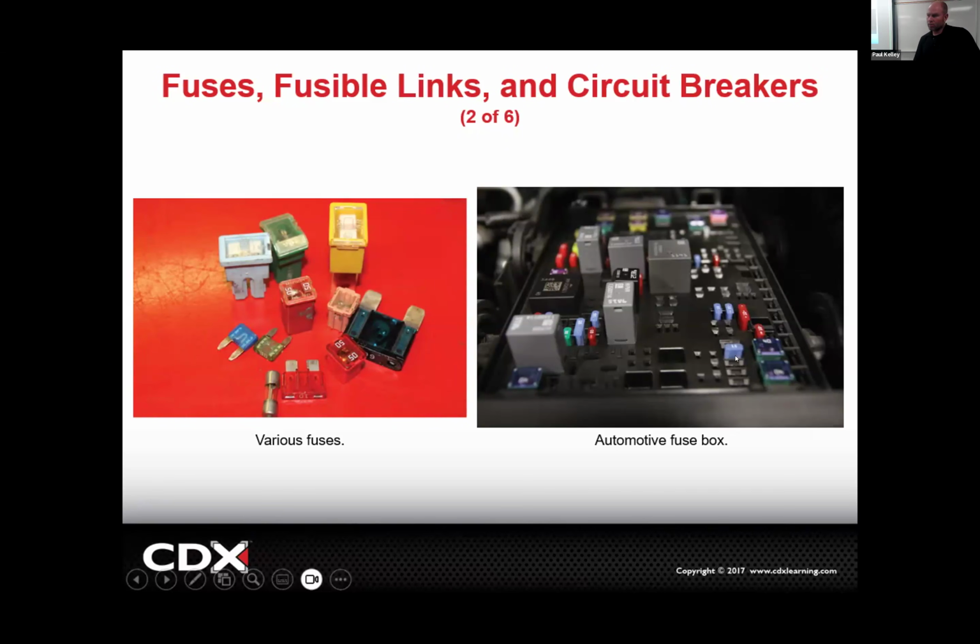And if we start to run out of room, it's like, how are we going to do this? They've made the fuses smaller, smaller, smaller. Now they're about as small as they can be. And we've started to have to combine them and double them up and do weird stuff. I see where one will feed the center, and then there's a fuse element to the right and a fuse element to the left, but it's all in one fuse assembly just to save space. It's gotten kind of excessive, I would say, but ultimately, if I show you how to test the fuse and the fuse is no good, then it's as simple as making sure you get the right type of fuse and replace it.